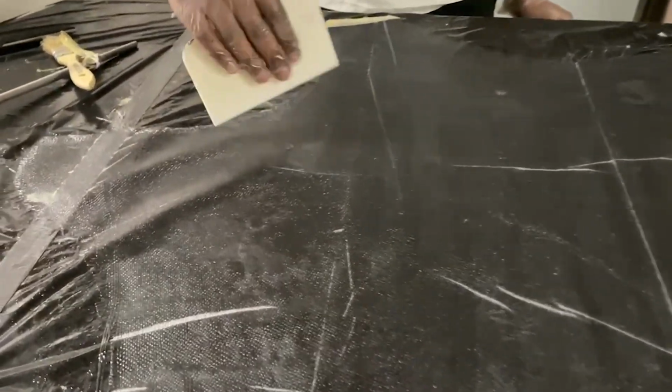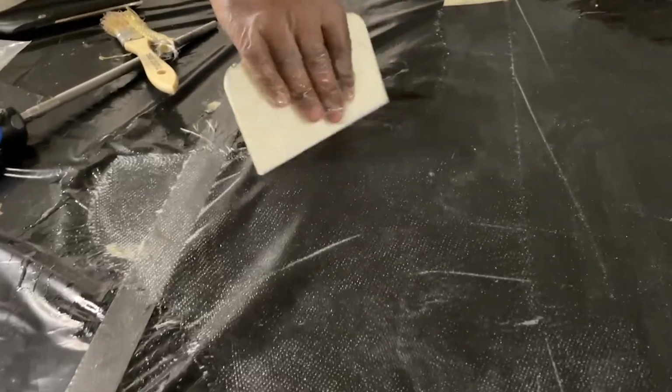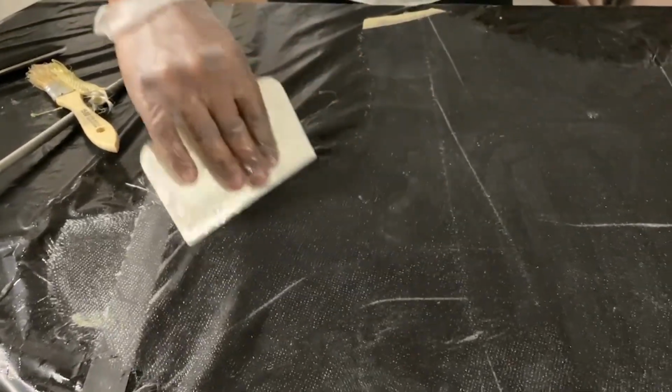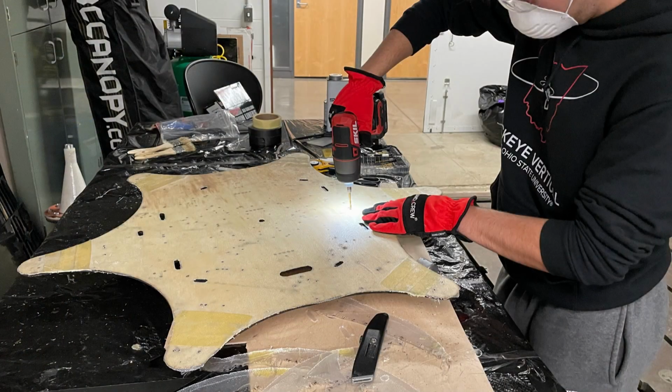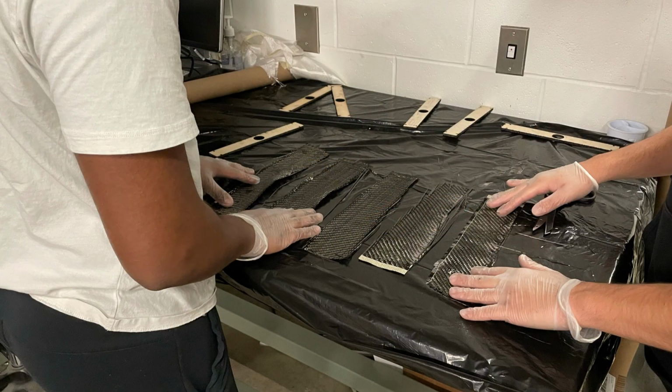Operating a drone, no matter the size, always compromises the safety of the team and others in the drone's flight vicinity. To combat this problem, we always notified others in the area of where we are flying and let them know to stay clear of the drone's flight path. Along with this, we make sure that we have a shunt plug on our system so that motors can be disconnected while the prop arc is obstructed. We also make sure that all competition team members are notified when the drone is armed and disarmed during flight.